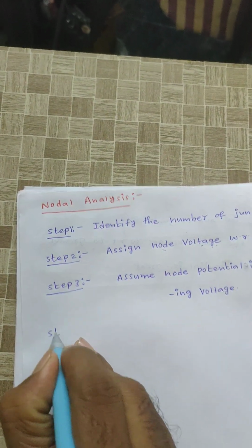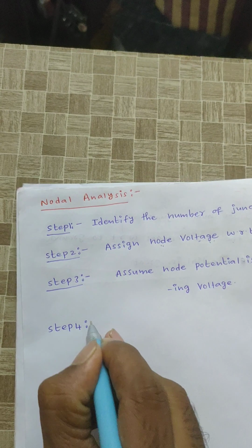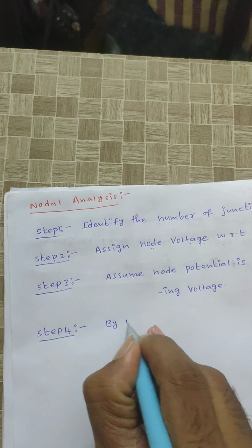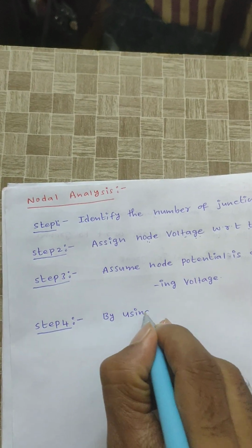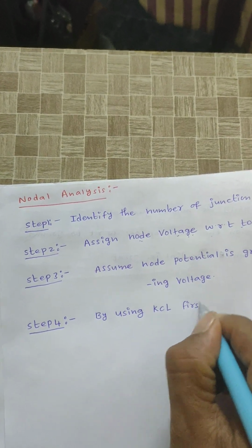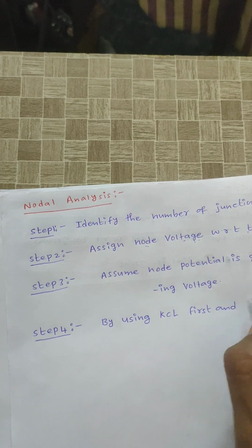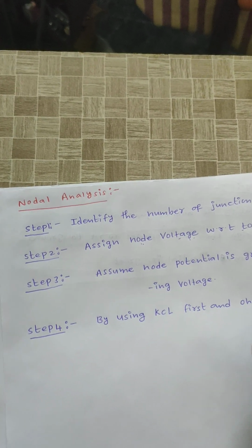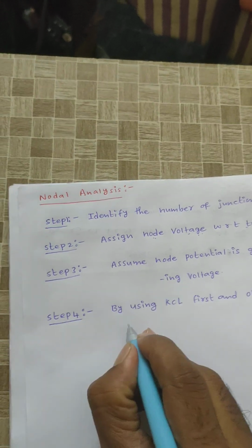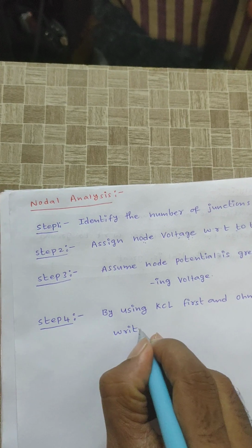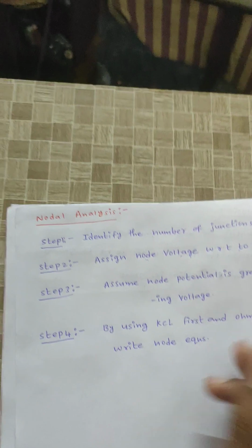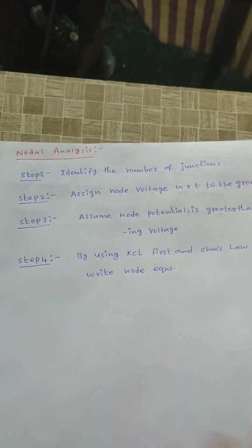Step 4: by using KCL first, and Ohm's law next, write node equations. Okay, that is about nodal analysis.